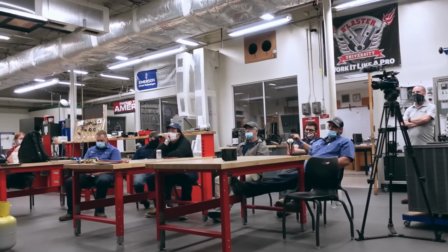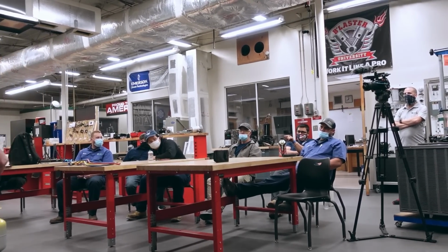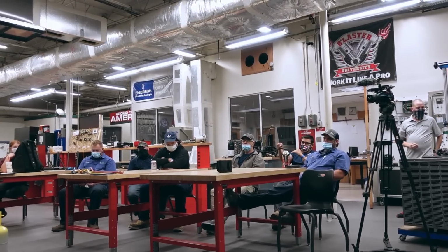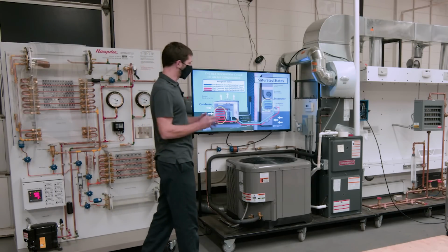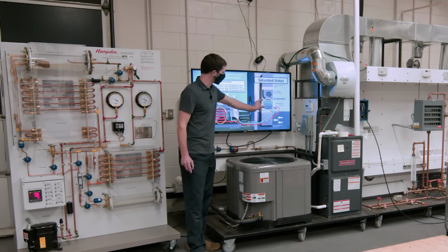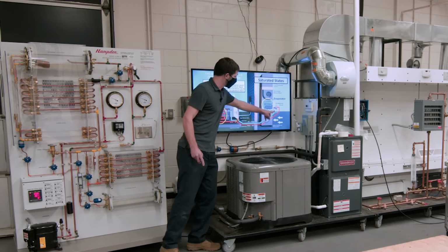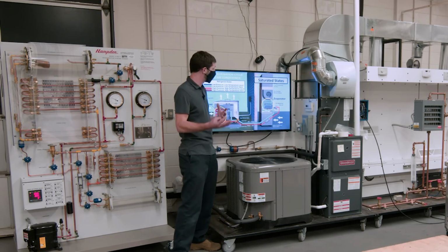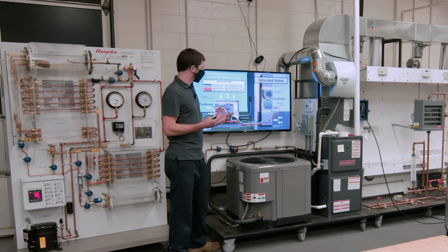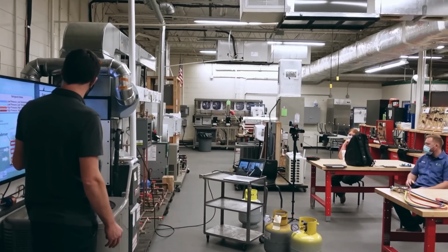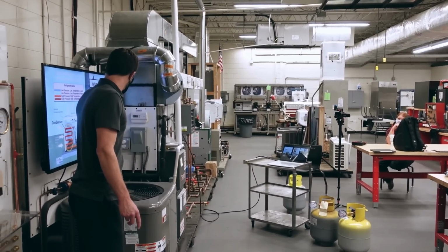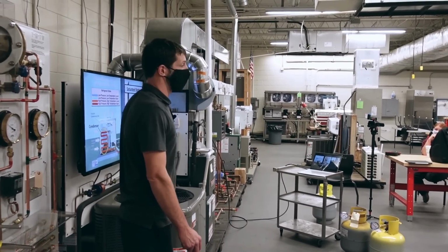I mean, it does. It's just basically you're allowing more liquid into the evaporator coil. That's correct. So you keep less vapor in the evaporator. Yes. You're allowing more refrigerant into the evaporator coil to absorb the heat load while keeping the superheat constant. You know, maybe average superheat for a thermostatic expansion valve might be 8 to 12 degrees, if it's operating correctly with a correct charge and an average heat load, but you may get 14 or even 16 degree superheat across that evaporator coil based on that thermostatic expansion valve.